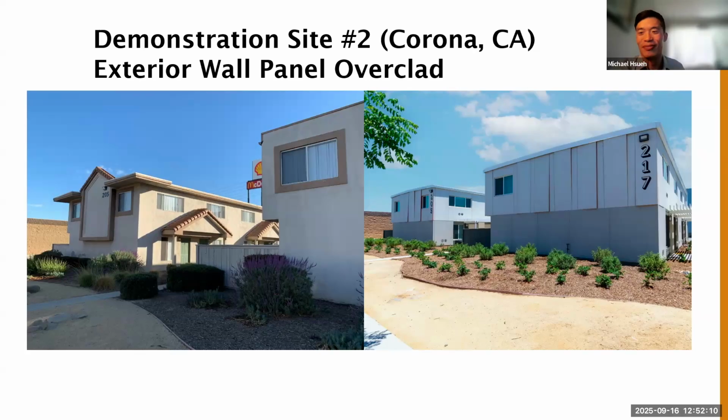I have another future retrofit project where I'm aiming to do a similar measurement and verification, and I would say that focusing mostly on temperature and relative humidity, and extrapolating from that to make some inferred guesses on moisture content, is probably more practical.